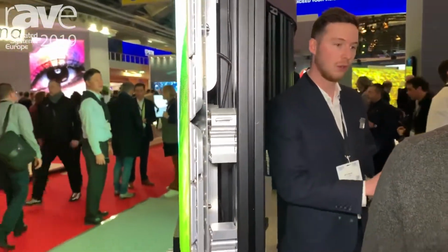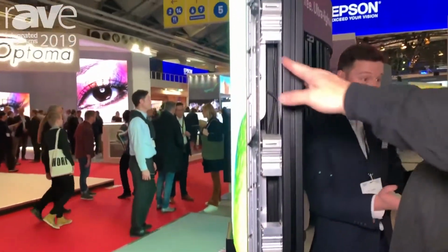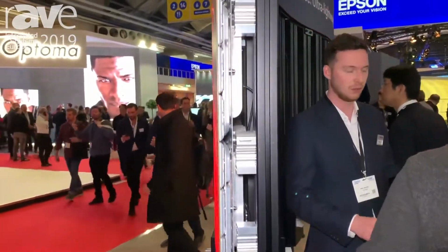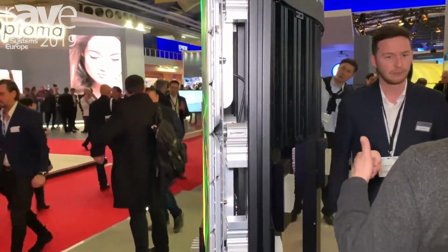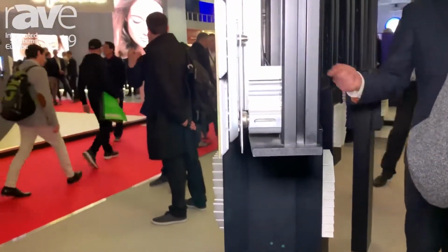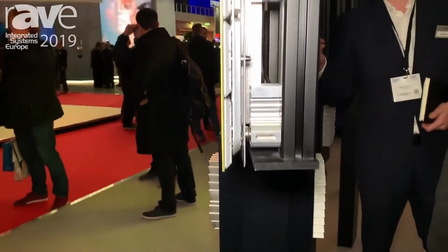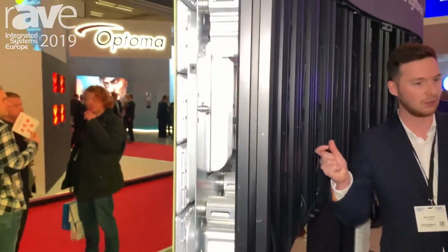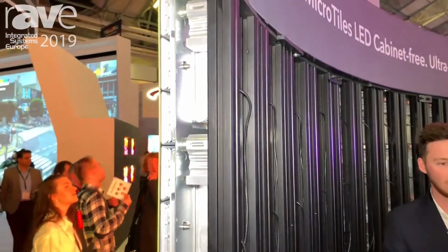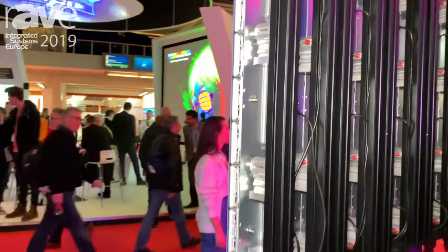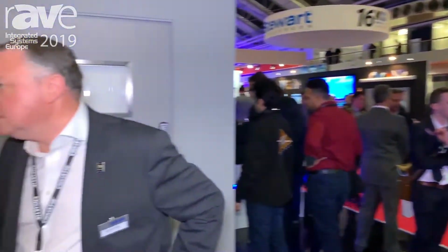Well, for us, we start with the pucks that we tie to the structure of the building or the installation that we're making. We put a metal frame, and then we put the tiles in front of that. So every tile then has 3 LED modules on board. That goes to an octo controller, which is the aluminium fins you can see below. They carry PoE power into the LED itself, and they're being driven by remote power supplies and, of course, remote data feeds. So giving you redundancy, reliability elements, and, of course, signal integrity throughout. Yeah, and so this can just grow whatever size you need it to be, depending on the application. And, of course, it can now be shaped.